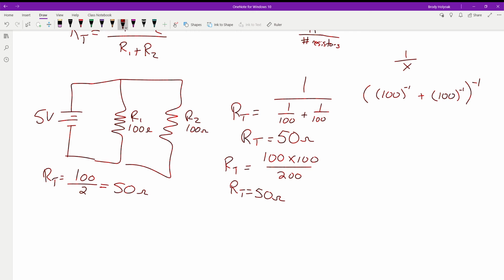So the idea here is, let's say, going with that idea, we put our voltmeter in parallel with this guy. So remember, when we're dealing with voltmeters, we want to try and get as small of a current as possible, because we're going to be leeching off that amount of current. So if we can get a very, very small current, like 1 microamp, leeching off of this guy.